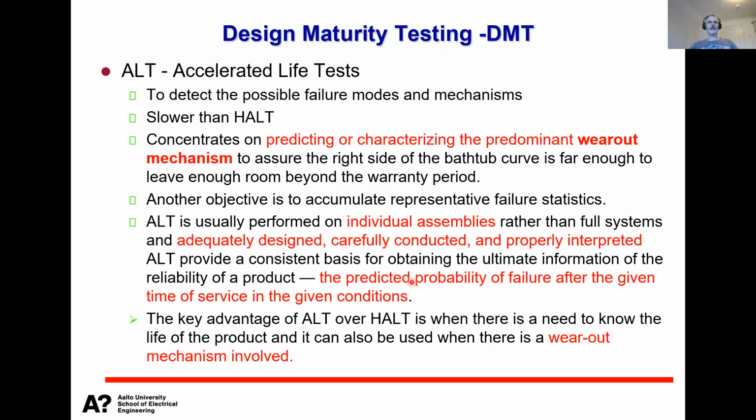The stresses are lower, so it is not over accelerating, and the target is to understand wear out mechanisms, not these random failures. So these three things are the critical key differences between HALT and ALT testing.